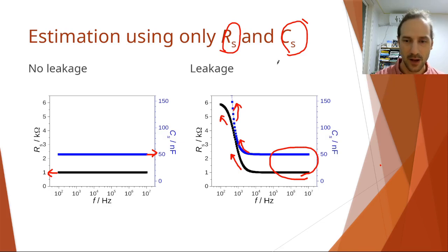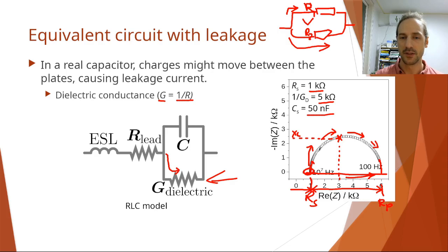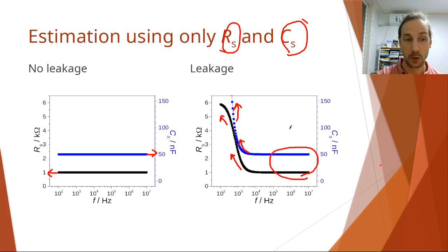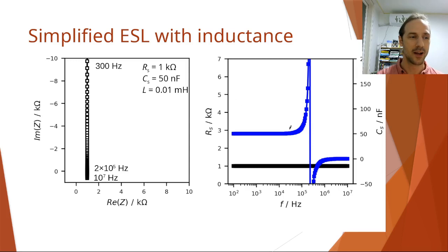And some of the experimental equipment can actually just measure impedance, and it will let you fit a semicircle here, and based on this semicircle, it will give you exactly your C and R and G, or two R values if you want it as a resistance value. Alright, so this is what we get, and then let's go back and check out the inductance.